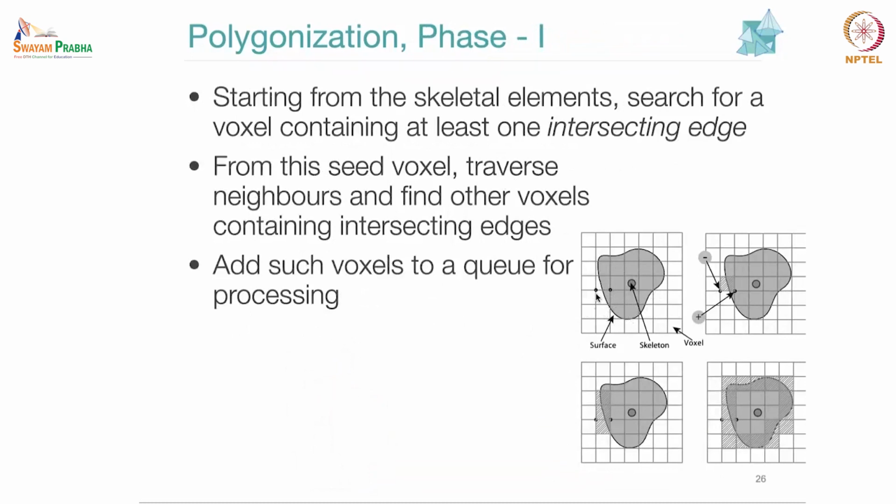I'm deliberately not saying 0 here because you might be interested in a non-zero ISO value, but I hope you can correlate it. If I am doing a 0 level set, then the grid that I'm selecting must have both negatives and positives on the 4 corners. A grid has 4 corners in 2D.